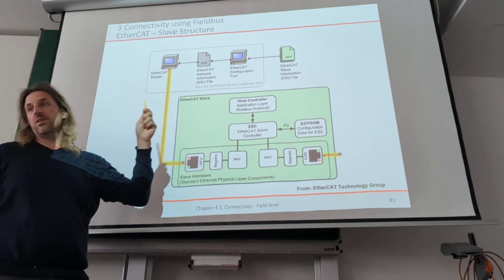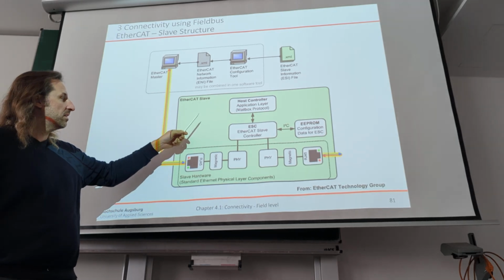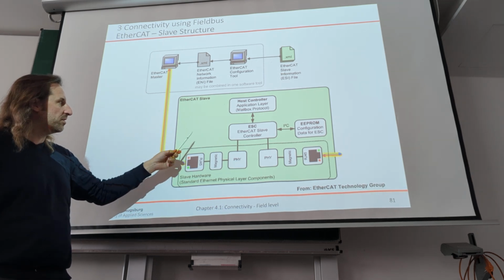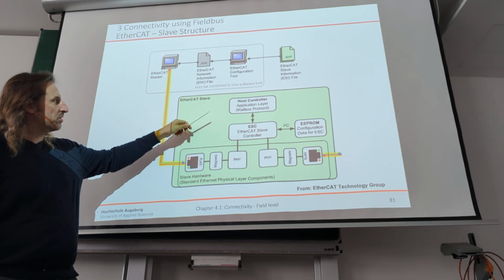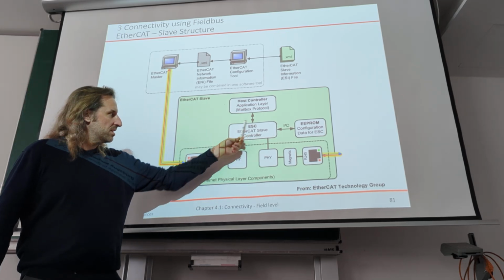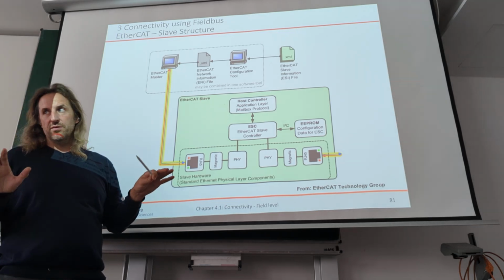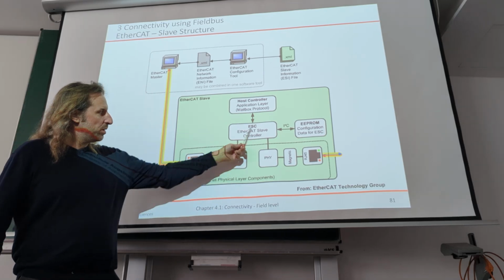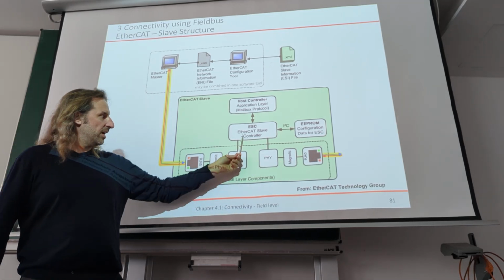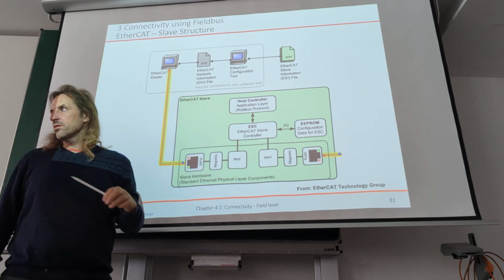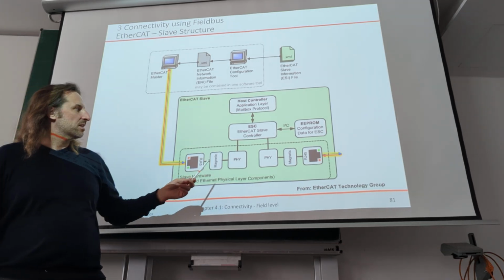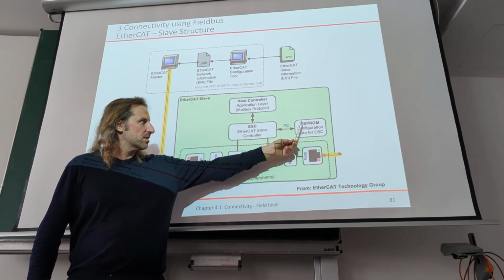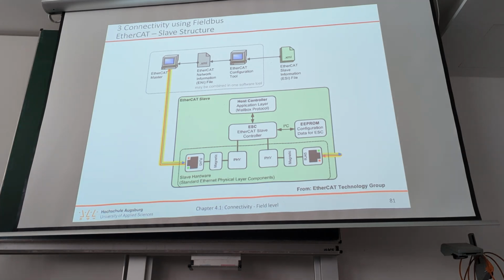It's programming, with a C SDK, but it's not so difficult to build these slaves, because you have these EtherCAT slave controllers, which are a fixed chip able to pass on the information, extract information and add information on the fly while the data is passing. The only thing you really have to do is configure these slave controllers, so you have to configure the information.